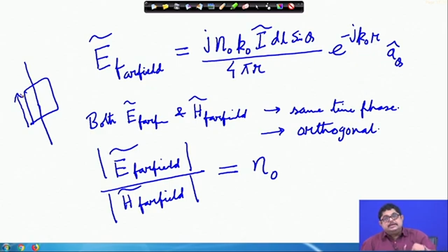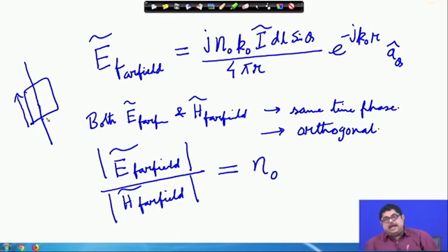At this instant, if this is plus, this is negative; next cycle this is minus q, this is plus q, and so on. So, there is a dipole formed here. In our current element also, due to this finite discontinuity, a dipole is formed, and that contributes here, but its effect does not go far, it stays near. So, this is the origin of the dipole terminology.